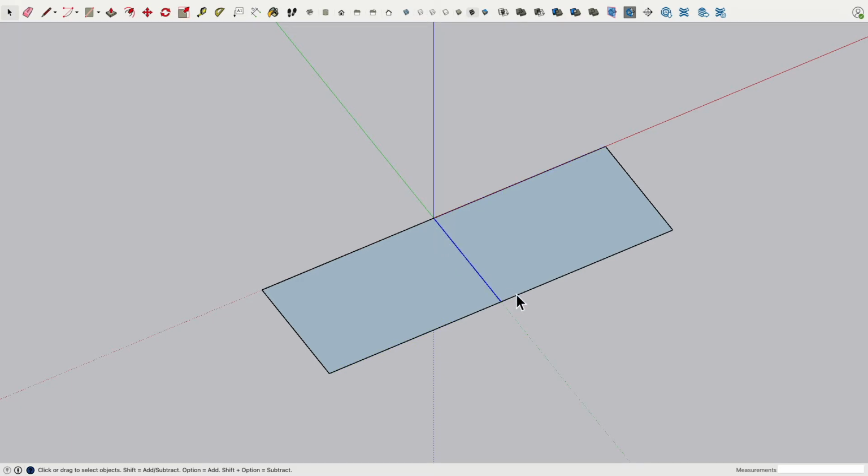We can select this line and then press delete, or we can also use the eraser. And now when we click into this field, you see it's actually one big fill. SketchUp automatically fused this together. This is very important to know. And when I click on these outer two edges, you see it is now one edge. Okay. Left mouse button, drag, press delete.